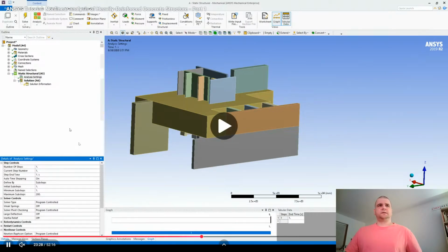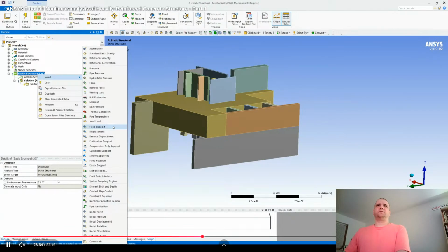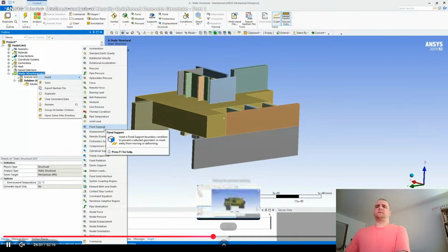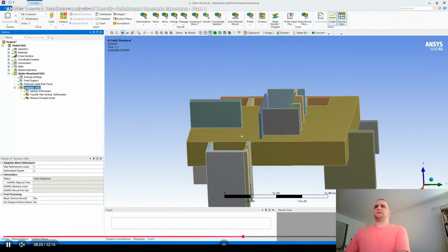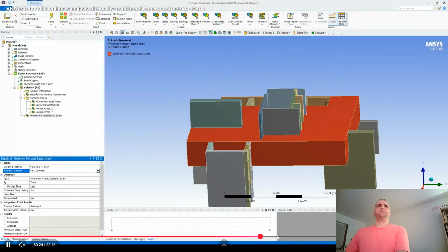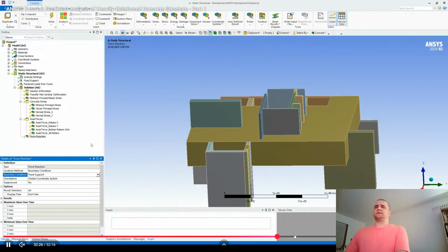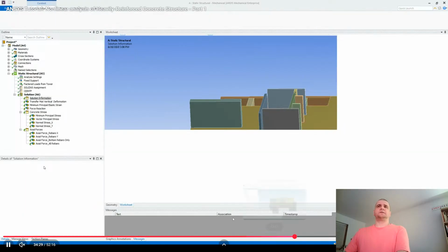So let's see a little here. Large deflection off? What? Please don't tell me you leave this off. Oh, he left it off. So we will not have fracture here. Remote force, yes, he's pressing this. Static, all right. So he didn't know how to do it in explicit.